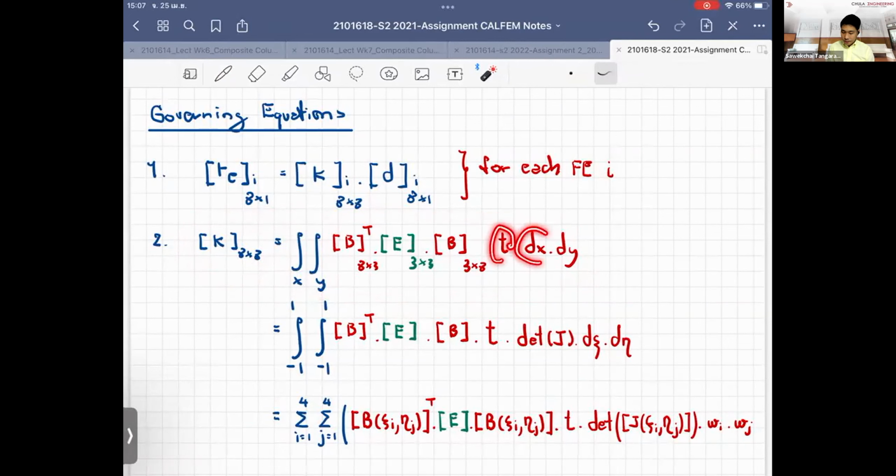You have the thickness, dx and dy, and the transformation matrix, which is derived from the derivative of your shape function, times the Hooke matrix, which depends on whether you're looking at the three-dimensional space or the simplified in-plane model, either plane strain or plane stress. So you have the E, which is the local stiffness matrix, to be 3 by 3, according to how you model the structures.